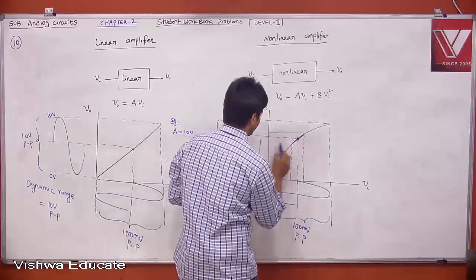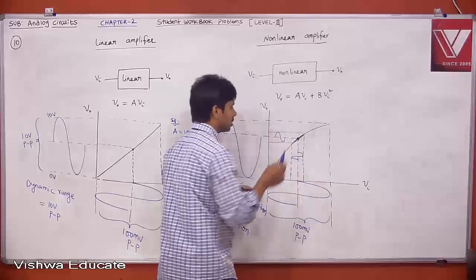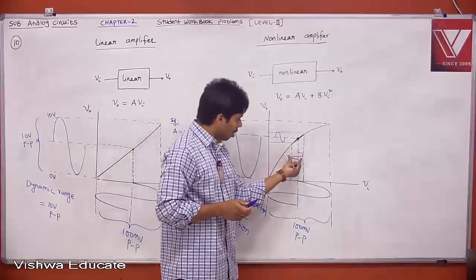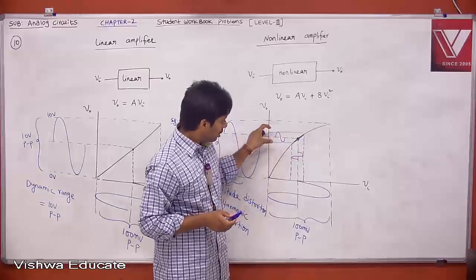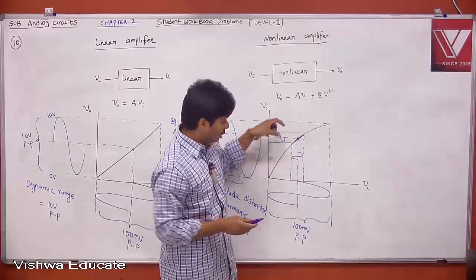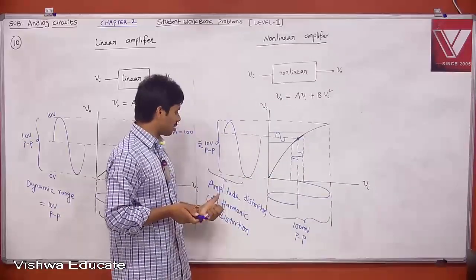Therefore when you apply a small signal, you will get the signal without any harmonic distortion. It means if you apply a small input signal, you will get an amplified version of that, but it still has some dynamic range, not completely rail to rail. If you try to utilize the complete rail to rail range, you will get harmonic distortion.